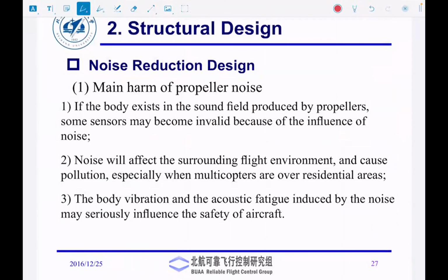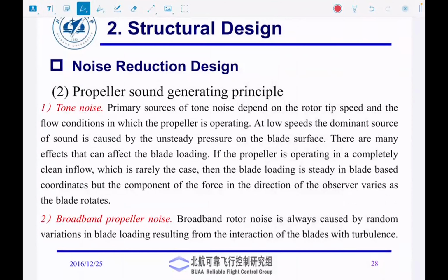And then the important noise generated from the aircraft is because of the prop, and you can sweep the blade, or you can increase the angle of the blade, and use these different noise reduction techniques. So basically, you can use NVH analysis, noise, vibration, and harshness analysis, and try to streamline the aircraft design, streamline the body, to minimize these sources of vibration.